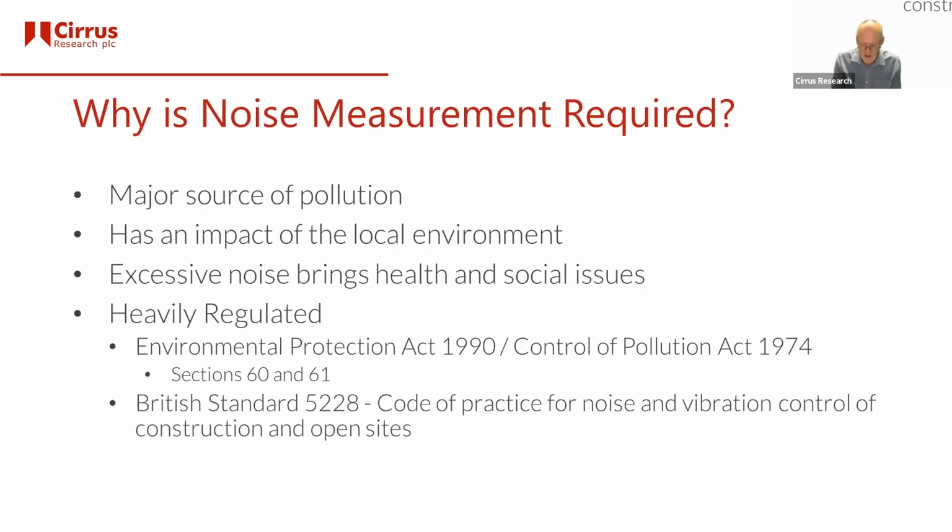And the two elements there, section 60 and 61: section 60, under the Control of Pollution Act 1974, is basically a statutory notice that the local authority will put on a site, which basically says, thou shalt do this. And what most developers do is they do the sensible thing, and they put forward, as I've mentioned, a noise management plan, which will state what they're going to do, how they're going to manage the noise, how they're going to make sure that they keep within reasonable limits for the local environment that they're in. And they will apply for a section 61, which is a binding agreement which says this is the way we're going to run our site.